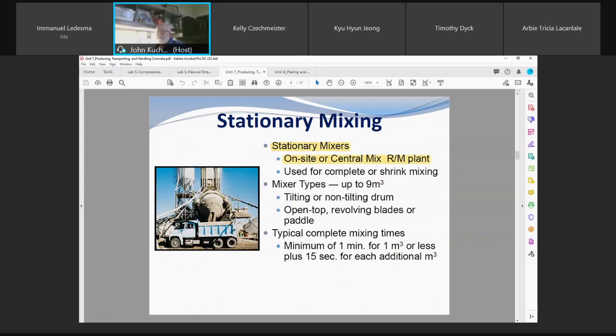Typically, you're going to use this for highway work or city work. You're going to be using a slip form paver, so you're going to be using stiffer concretes to begin with. Okay, when you're using a slip form paver, which is an extruder, the concrete goes through the machine and you get 200 millimeter thick pavement out the back, no forms on the side. You don't want it to stand up. Okay, so no, that's acceptable.